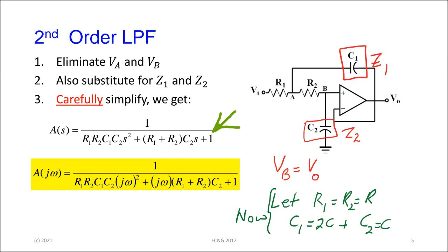Okay, so when you get to that point, of course, once this is in the Laplace domain, and we want to get the frequency response, the frequency transfer function, or the Fourier transfer function, we make the substitution S equal to j omega, and we get A of j omega is here. And the point I was making for those of you who were in the signals class this morning, keep the j omega in brackets, right? So when you square it and cube it and so on, sometimes the j will disappear as a minus, because if it's squared it will appear as a -1. Other times it will be there as j or minus j, depending on the power, right? So keep that in a bracket.